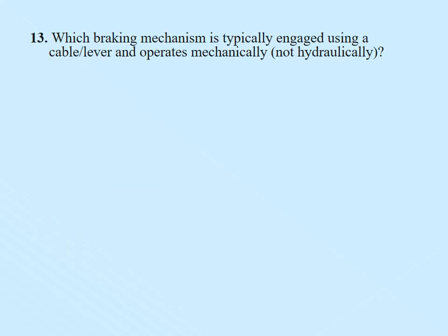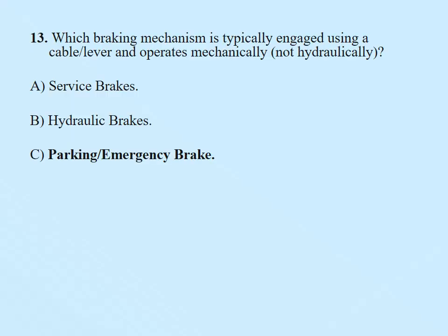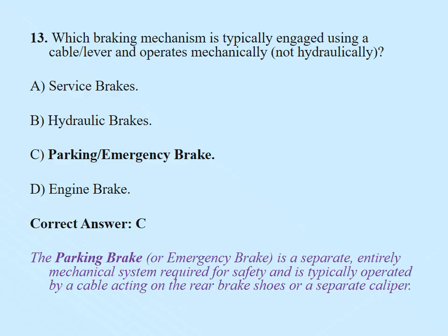Question number 13. Which braking mechanism is typically engaged using a cable or lever and operates mechanically, not hydraulically? A, service brake; B, hydraulic brakes; C, parking or emergency brakes; D, engine brake. Correct answer is C, parking and emergency brake. The parking brake or emergency brake is a separate, entirely mechanical system required for safety and is typically operated by a cable acting on the rear brake shoe or a separate caliper.